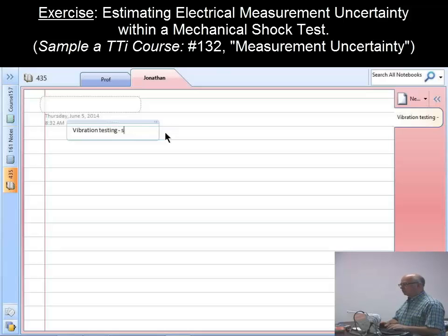A lot of times it'll be a low-level quarter G signature sweep, and it's usually done before and after tests. A lot of times that'll tell us if there's any type of problems with the workmanship, or if something broke during the actual shock or random vibration environment that it was exposed to. Is this shaker shock? Shaker shock, yes, sorry. So our lab here, we have a couple of different Ling 335 and 340 electrodynamic shakers. And when I say shakers, they're basically like a big speaker head.